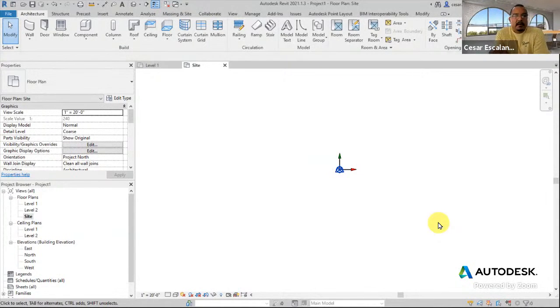So this is the easy way of aligning elements, but more often than not, this does not happen. You just bring a CAD file, snap it to the location of these 3 points, save it, and then send that file to the rest of the consultants and say, hey, this is the origin. We're all going to start at this point, and use this as a reference to where the point is located. And no need to go into this whole discussion on how to align them afterward.